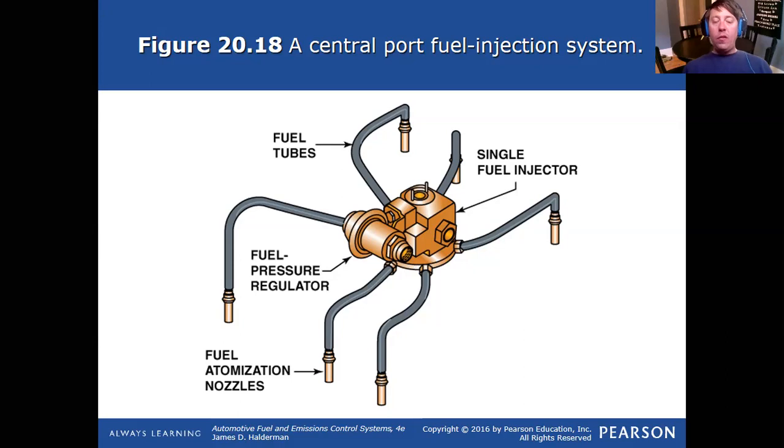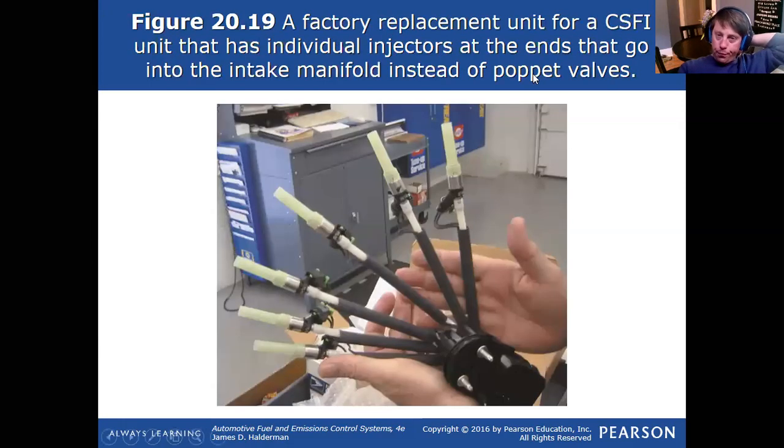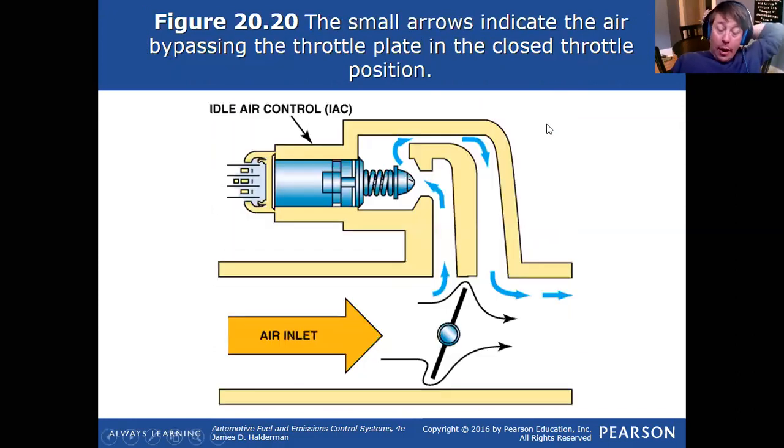Even they just hear a whine sound coming from the starter, because the engine's trying to compress the fuel that's sitting in that cylinder. And in extreme cases, if the entire body of this thing snapped, it would just dump all that fuel right into the crankcase. And the first time I saw that, it was an eye-opening experience, seeing like 3 gallons of fuel come out of the crankcase. Of course, it was mixed with oil, but it's not a sight you ever want to see. Didn't necessarily cause permanent damage when that happened, but it's not good for the customer by any means.